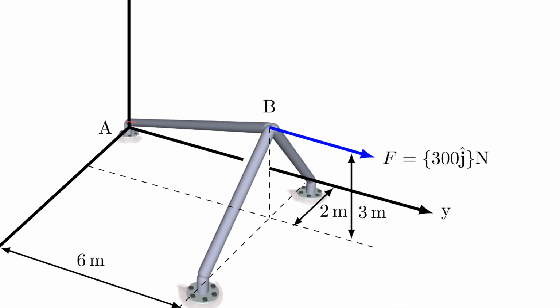So I want to identify pipe AB for you here, which once again is not parallel to the force. So what that means is that if we extend that pipe, which I'm going to do here now for you, there is a triangle that the pipe forms with the force. And if I want to complete that triangle, let me draw the perpendicular component to it. So I also have this part here. And so now I have 3 parts, which is technically vector decomposition, or is nothing else than vector decomposition.